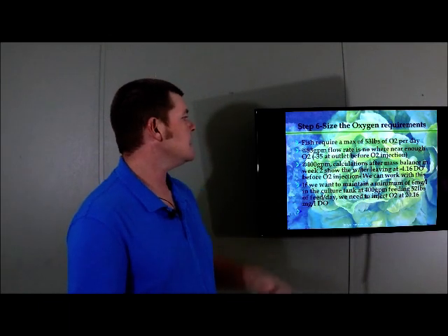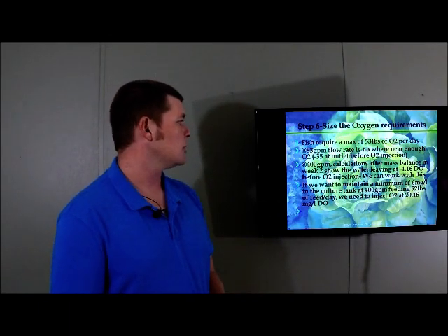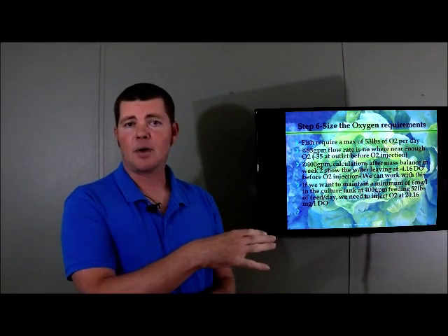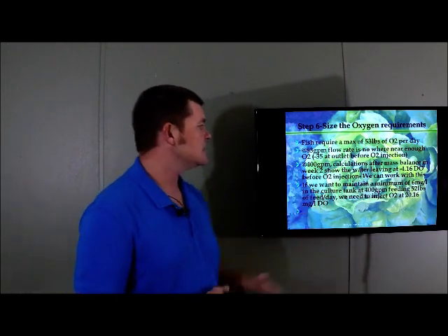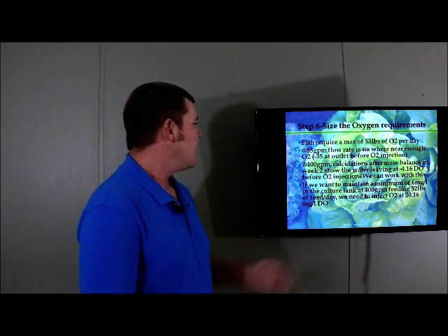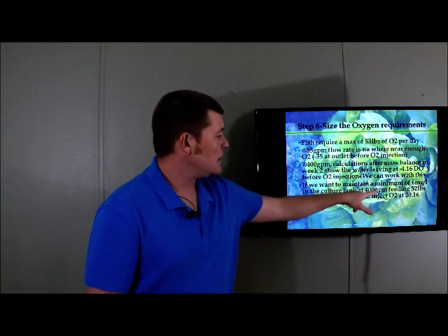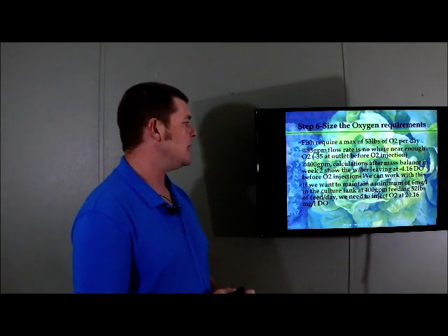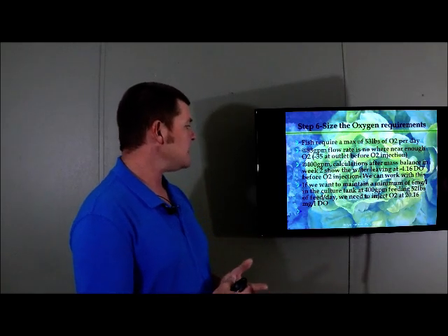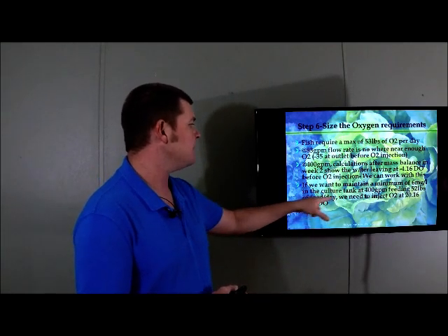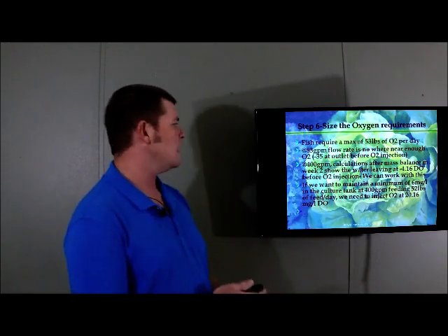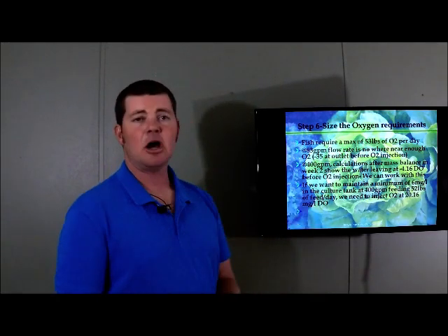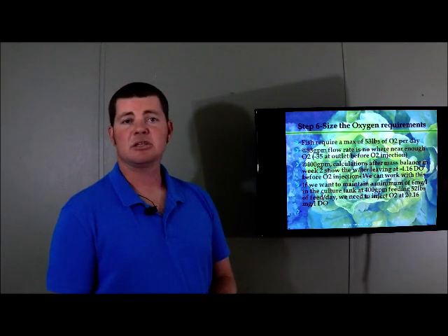If we want to maintain a minimum of 6 milligrams per liter leaving the tank, okay? So nowhere in the culture tank is it going to be less than 6 milligrams per liter. Then, we have a 400 gallon per minute flow rate, and we're feeding 52 pounds of feed per day, we need to inject oxygen at 20.16 milligrams per liter of dissolved oxygen.